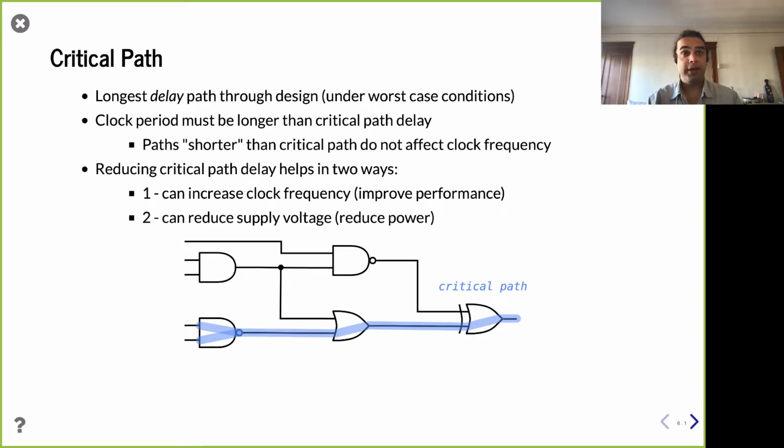So even though in a modern era we're mostly power limited or energy limited when we're designing, reducing the critical path is extremely important because it's going to help set your frequency. It's also going to be an opportunity for you to perhaps run slower to save more energy, right? So you really want to get a handle on these critical paths.